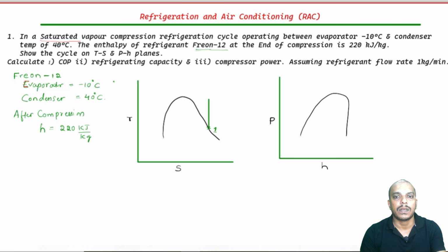Then this will be outside vapor dome, it will be constant pressure, looks like this in a TS diagram. And inside vapor dome, temperature and pressure both will be constant. So, it looks like this horizontal line within vapor dome. So, 2 to 3. Then remember 3 to 4 is a throttling, which is isenthalpic process where enthalpy remains constant. Alright, this is pressure constant by the way, 2 to 3, this is entropy constant.